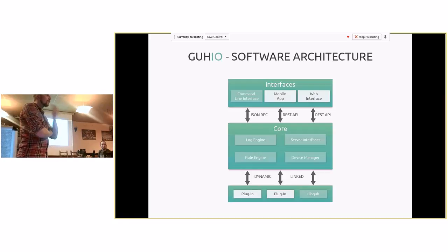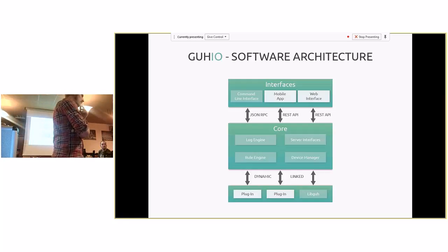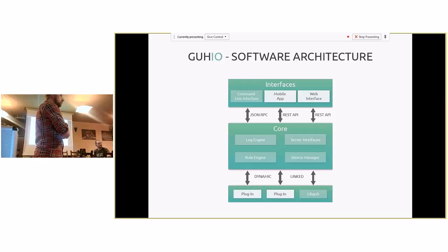So if I have the communication from the edge router to the sensor, is it somehow secured or not? At the moment, it's just the security of the 6LoWPAN. I see. Standard. Okay. And DTLS, for CoAP? Yeah, it will also be implemented next year, but not at the moment. There is no encryption between the devices and the edge router. No encryption between the sensor nodes and the edge router. Between the server and the edge router, it's encrypted, also the communication between the interface and the edge. But I think in 6LoWPAN you can have SSL, so at least something. Yeah.